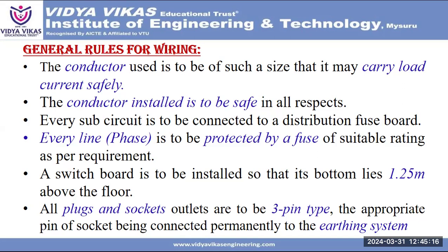Third, every sub-circuit is to be connected to a distribution fuse board. Of course, every line or phase is to be protected by a fuse of suitable rating as per requirement. Of course, we connect each and every phase wire through a fuse.